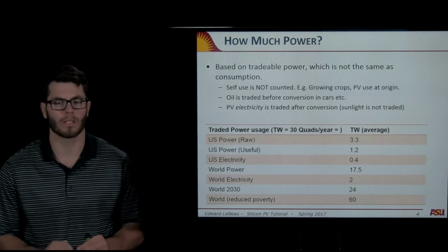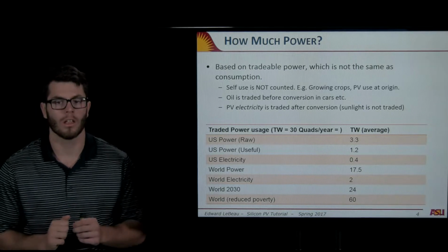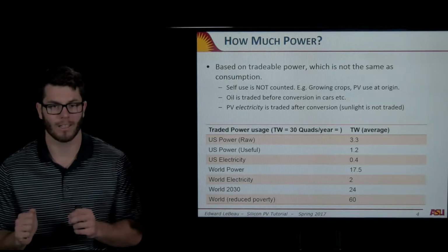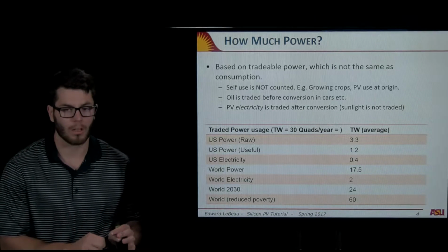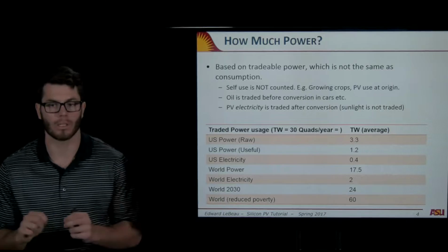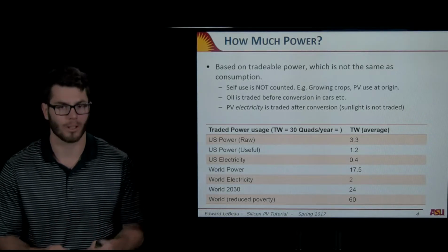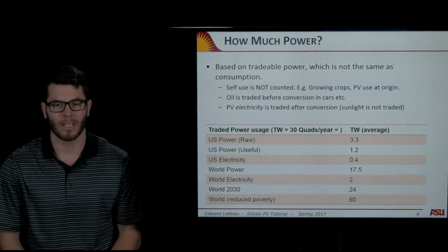So real simple, just think of it like this. Kilowatt hour, energy, joule. Kilowatt, joule per second, right? So that's a kilowatt, or power, is how much energy you could make per unit time. Kilowatt hour, or energy, is joules, okay? So let's keep that straight. We don't want to get those confused.